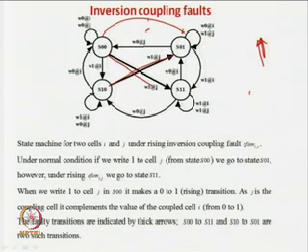In this case, you are writing the same thing as I told you. You write a 0 to a 1 in the cell J, and unnecessarily this also gets complemented. Similarly, here you are writing a 0 to a 1 in cell J, and the content of cell I is also getting changed from 1 to 0. So we should have gone here. If you want to write from 0 to 1 in J, you should have gone here, because the content of I you are not touching with this W1 at J, but because of this coupling fault, the content of I is also getting complemented. So you have these two extra transitions for this up transition fault.